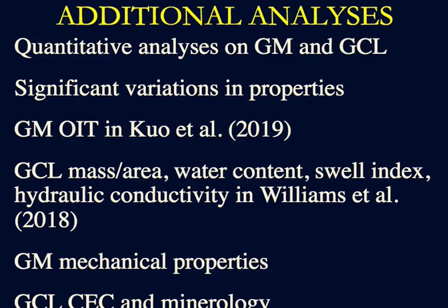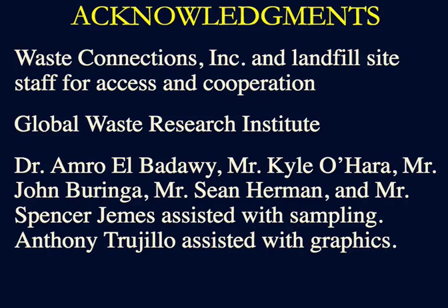The GCL mass per unit area, water content, swell index, and hydraulic conductivity are reported in a paper in Williams et al., 2018, just to be presented this fall. The geomembrane mechanical properties are being conducted currently, and the GCL cation exchange capacity and mineralogy have been completed and will be reported elsewhere.